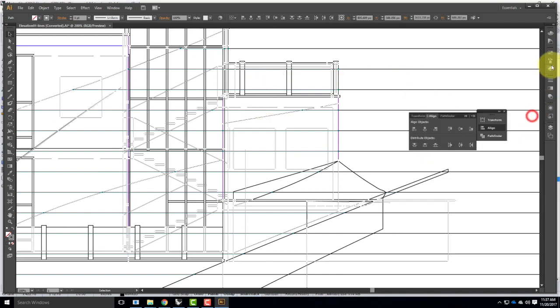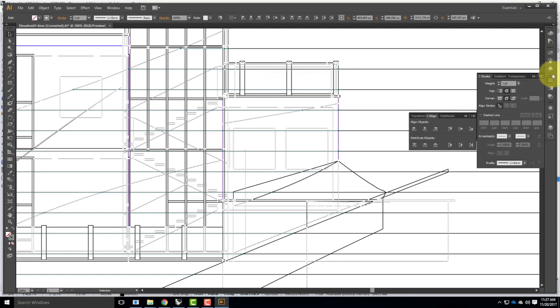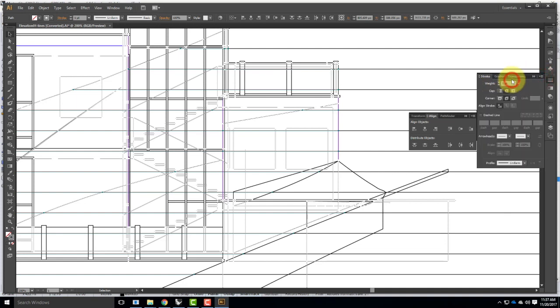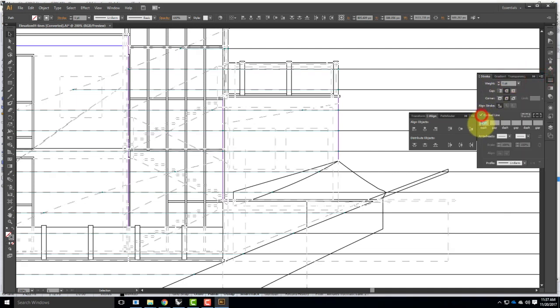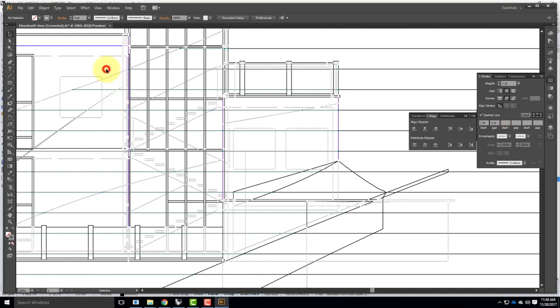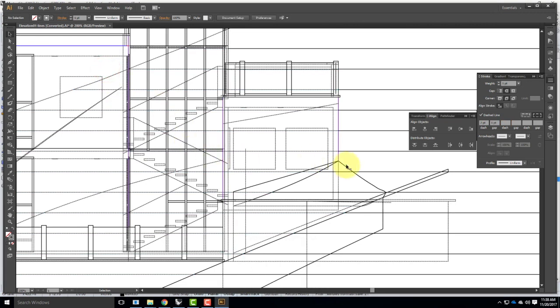So I'm also going to go in and change the line stroke a bit. When I click on stroke, if you don't see this menu, you might just see the weight. If you don't see it, go ahead and click on Show Options. I'm going to convert these to be a dashed line. And the dashed line I'm going to do is a 1 point, or maybe a 2 point by 1 point, so that they're kind of a faint little dashed line. If I click off so nothing's selected, you'll be able to see them a little bit better now. They're still a little too heavy.